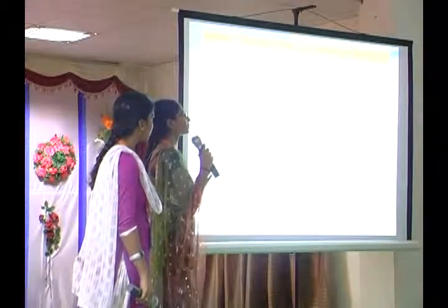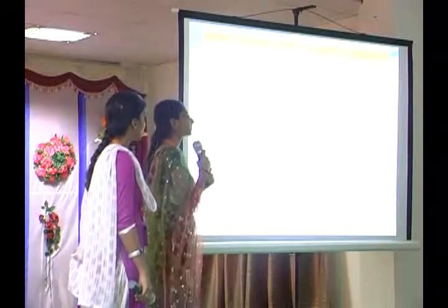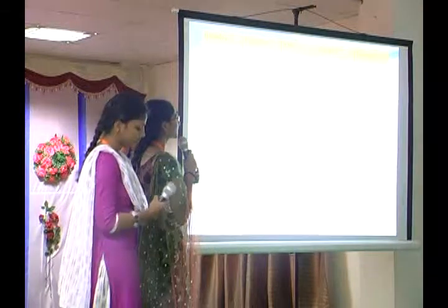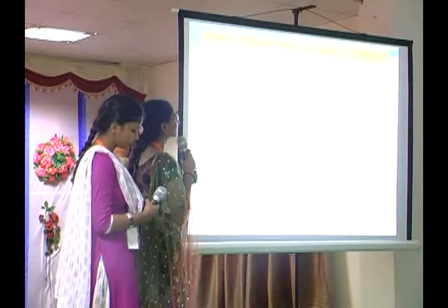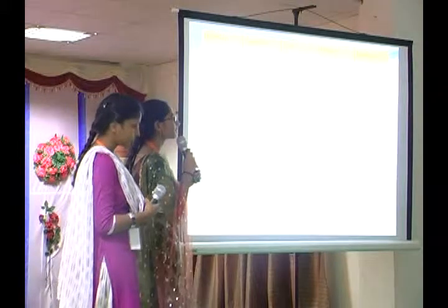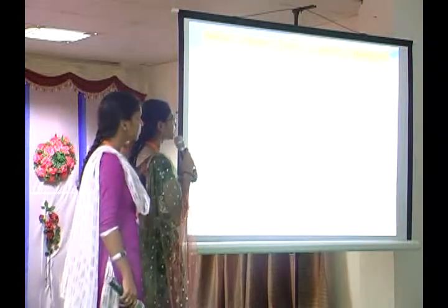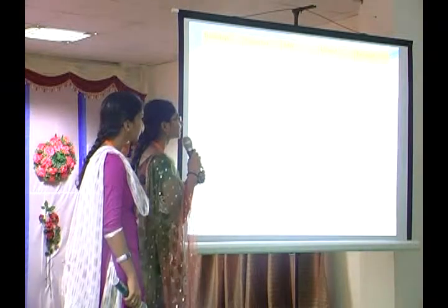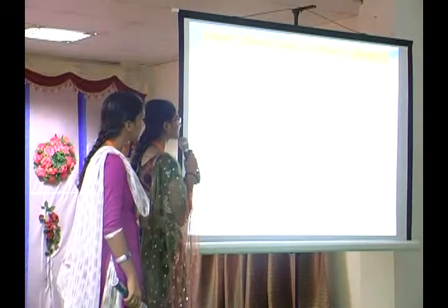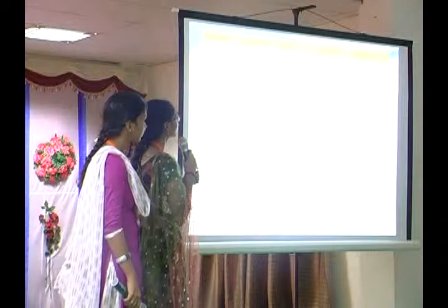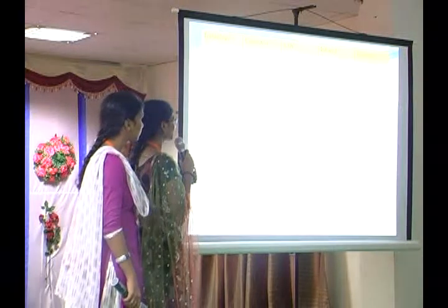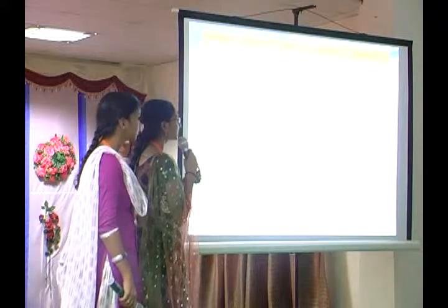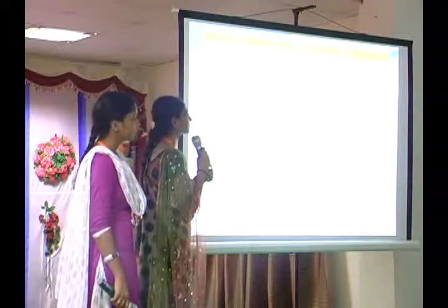This is the preview comparing the various technologies. Transparency: in resistive touchscreen, the transparency is only 75 to 85% compared to other types. It is very low. Regarding resolution, infrared touchscreen is limited, whereas capacitive, SAW and resistive are good. Surface contaminants: capacitive is resistant to moisture, whereas SAW is affected by moisture.